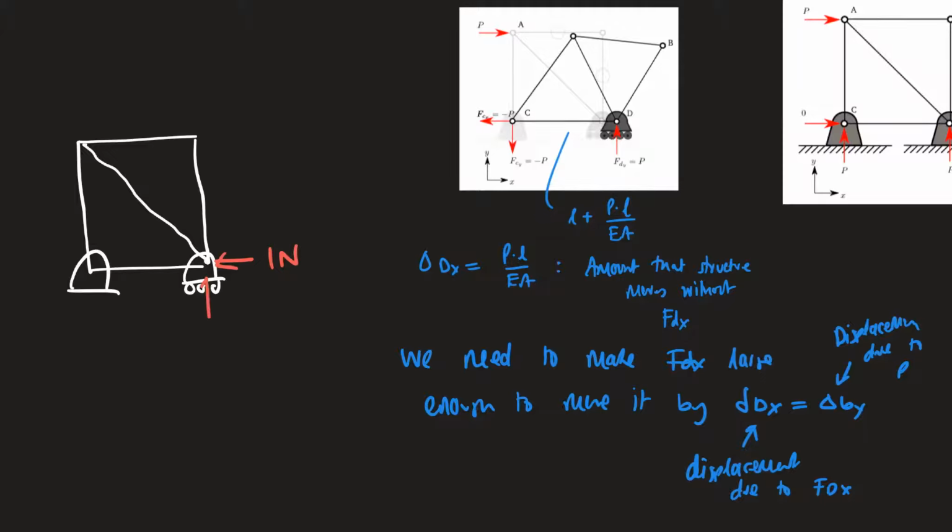We're then going to have a look at the reaction forces. We could solve for the reaction forces. We've got 3 again. It should be apparent from this that actually there's only a single member that can take this load. So these are all zero force members for this case, and there FCD is going to be equal to 1 Newton in this case.